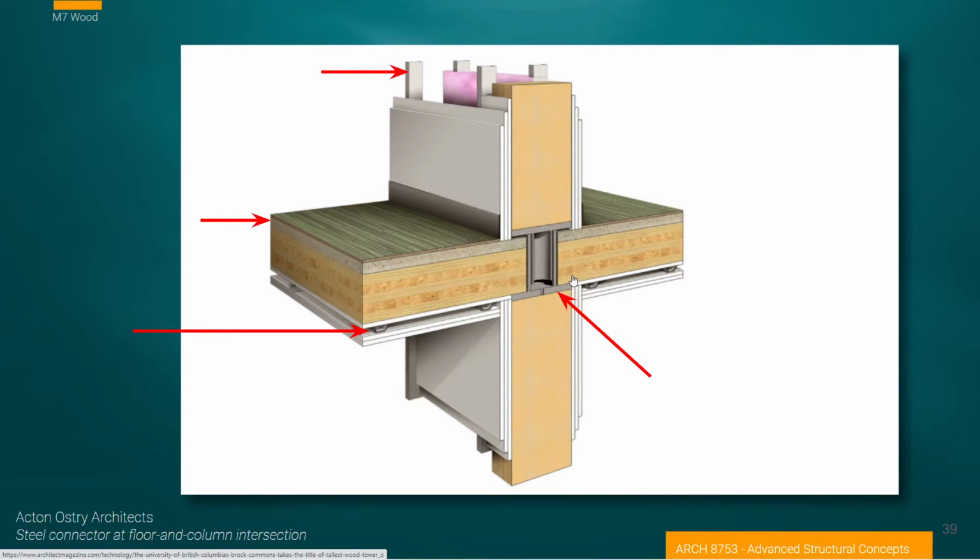And then you get another feeling for this idea of mass timber systems and what goes into, in this case, fire protecting them, maybe from a fuel source, but also insulating for sound. So we have a really heavy column. And this is where some issues come up about how much space is taken up by these mass timber systems compared with conventional fabrication.